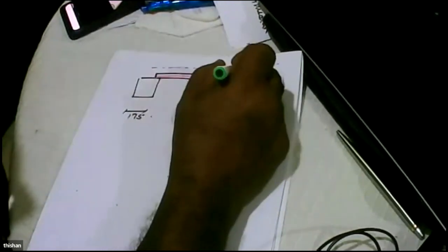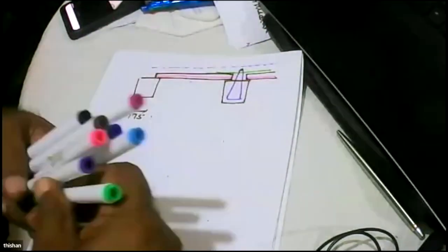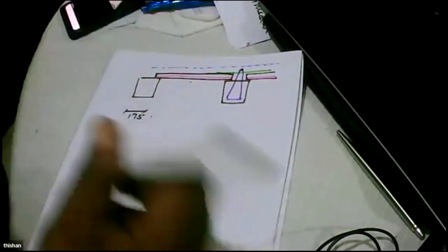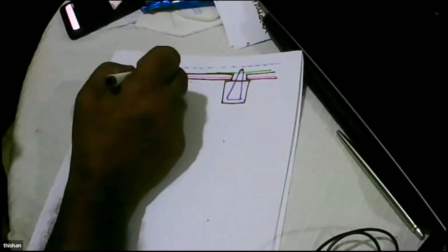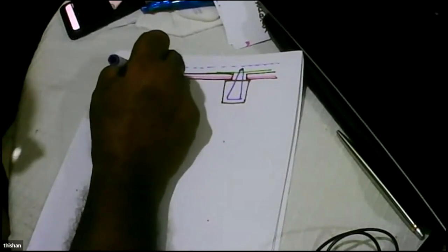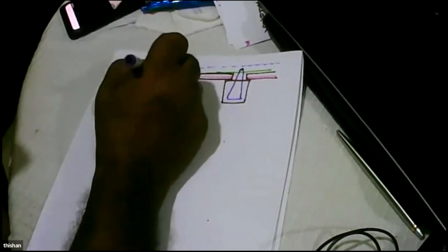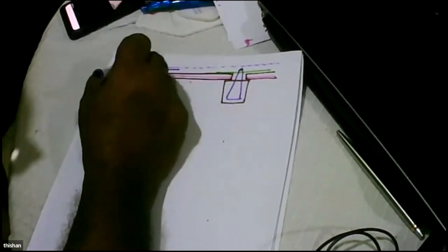But when you do this, you will find that this reinforcement is having a lot of cover. Then what we thought was, okay, let's have this reinforcement, and let's have a reinforcement at this level to lock it. And the continued reinforcement goes above it, so it will act as a top reinforcement.